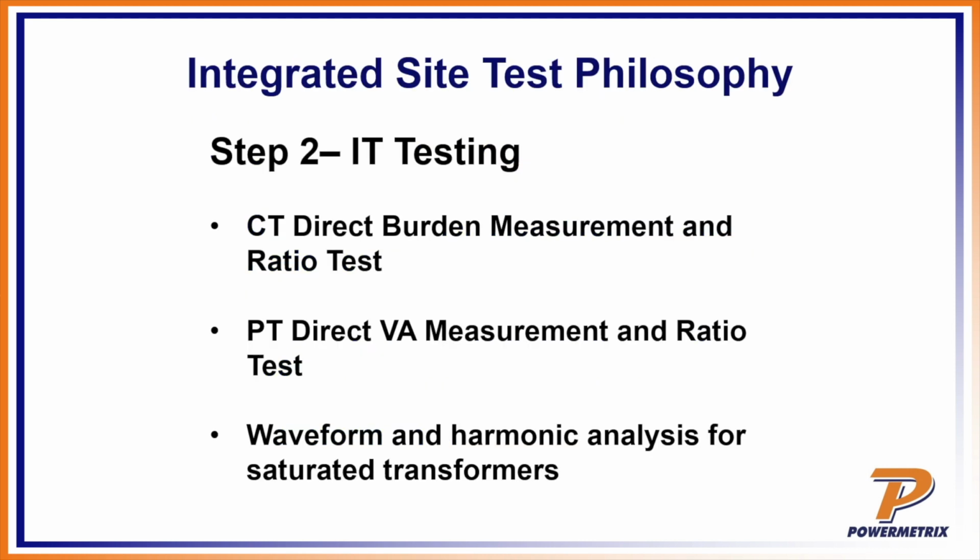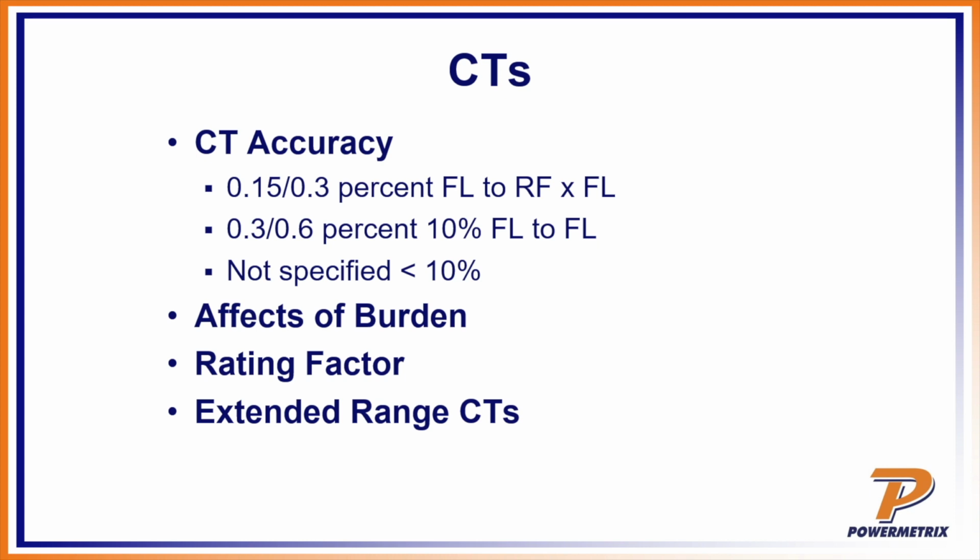The second thing that we want to look at in our integrated site test philosophy is my instrument transformer testing. So I want to do a CT direct burden measurement and a ratio test. Same thing with a PT, a direct VA measurement and ratio test. And I want to look for waveform and a harmonic analysis for saturated transformers. So CTs, there are a lot of things to consider with my CT.